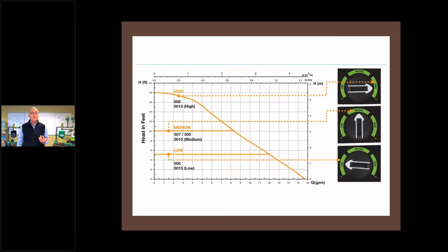So now, if I'm going to do it with one circulator, all I have to do is overcome 5.2 GPM. And we focus on the highest head loss. So our highest head loss would be 6. So if I decided to do a 0015E3 and use one circulator at 5.2 GPM at a head loss of 6, I could either set it at low and it's going to be performing right here, okay?